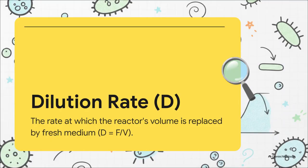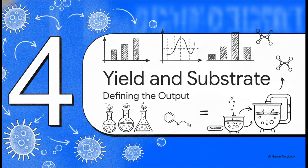And this brings us to exactly how we mathematically control this continuous environment. We use a metric called the dilution rate, or simply D. The math here is incredibly straightforward. D equals F divided by V. F is the flow rate. Think of it as the faucet feeding fresh nutrients into the tank. And V is the working volume of that tank. This single number tells us exactly how fast the liquid inside our bioreactor is turning over. Which leads us straight into section 4, biomass yield and substrate.